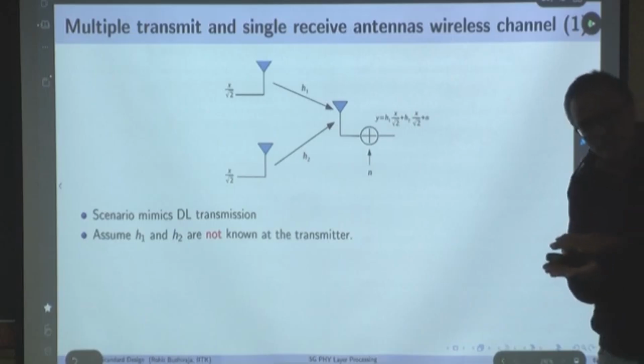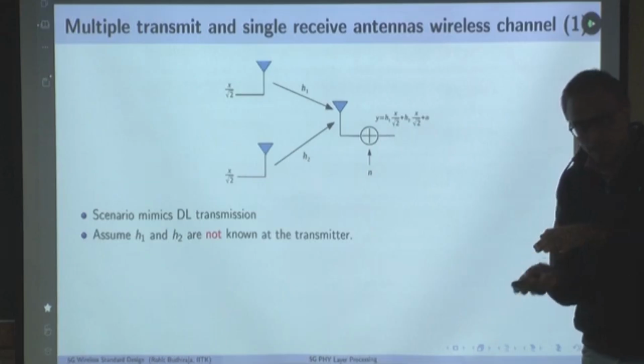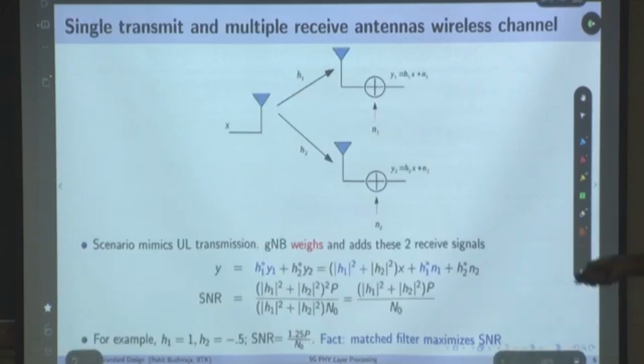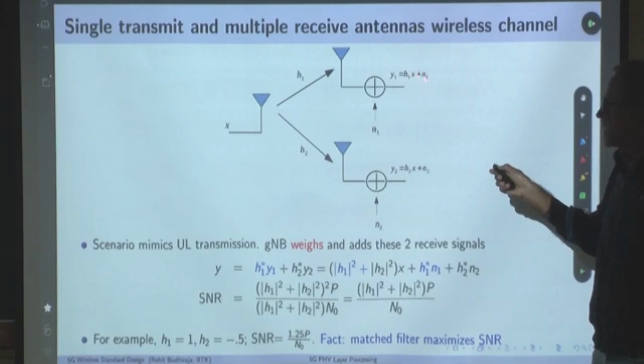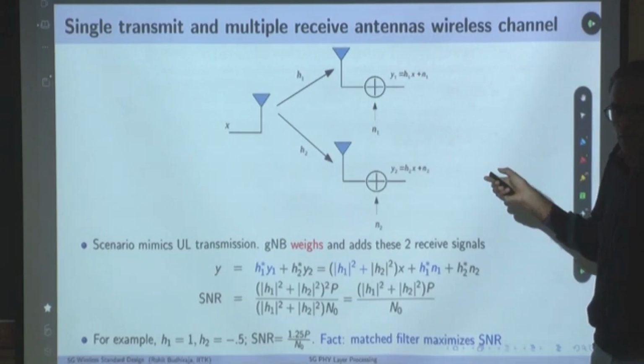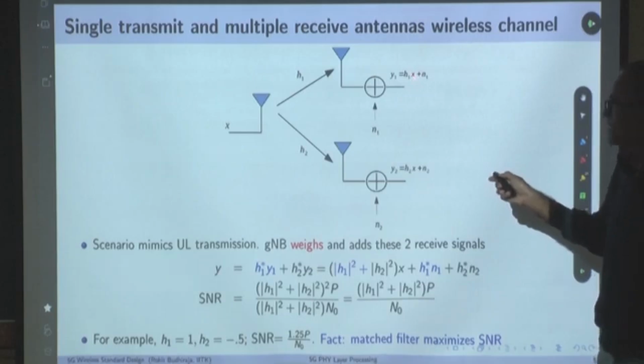The receiver is receiving the signal. So, it is easier for the receiver to estimate the channel, because who has the received signal? Let's even go back, I think that's important. Y1 is equal to H1 x plus N1. Who is observing this channel? The receiver. Later I will show you when these pilot signals come. I do not remember whether we discussed in this class, if x is a pilot signal, let us say x is set to 1.